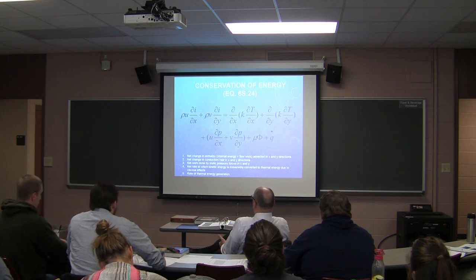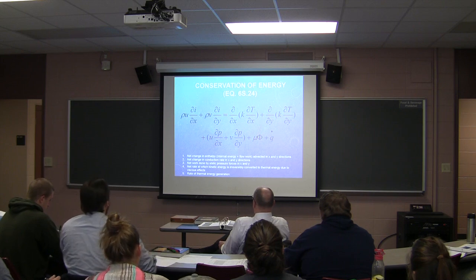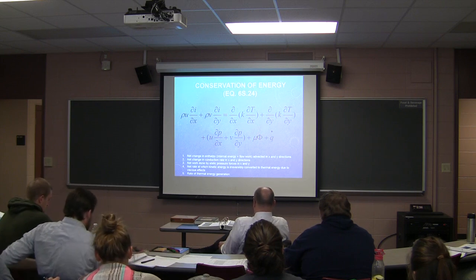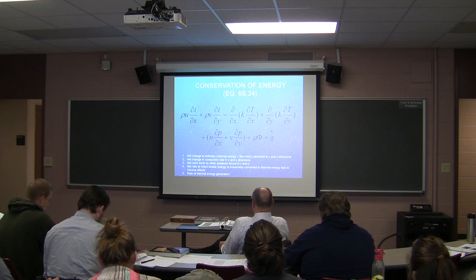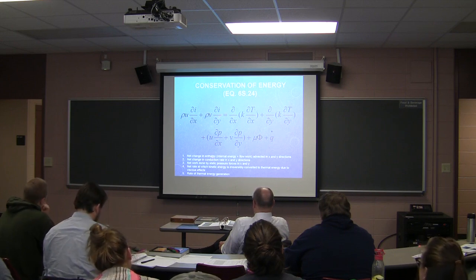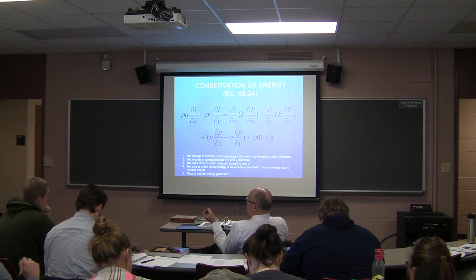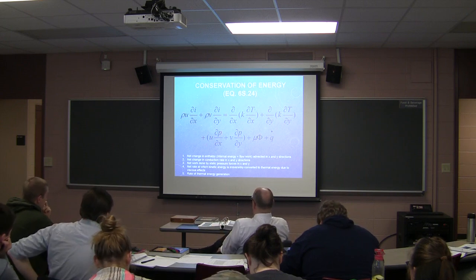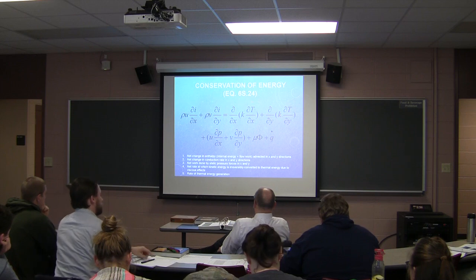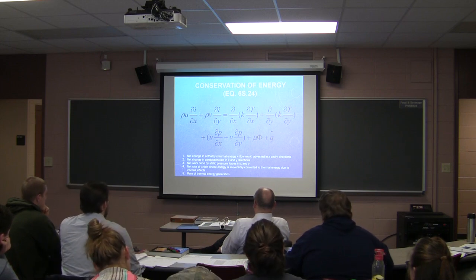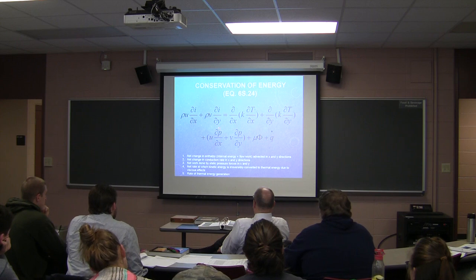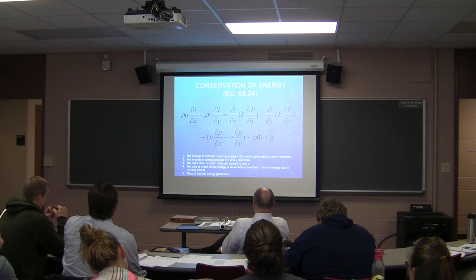This is a refined version of the conservation of energy term, where the first two terms here represent the net change in enthalpy, where the internal energy and the flow work terms associated with advection have been combined and now are contained in these two terms for the x and y direction. Here's your conduction, and this is the net work done by the static pressure forces, your viscous dissipation.